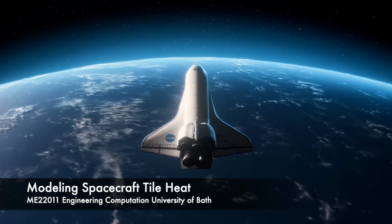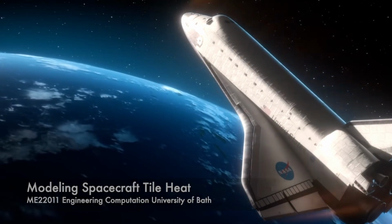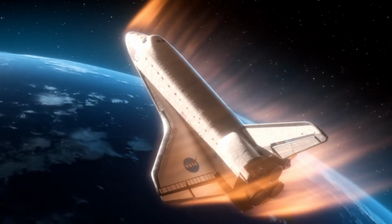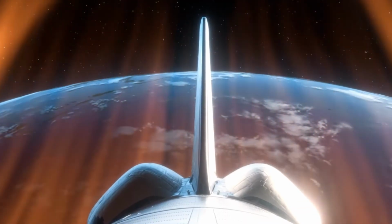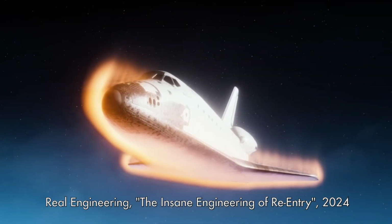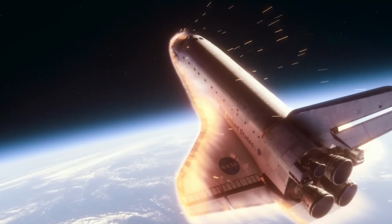During spacecraft re-entry, extreme heat is generated due to atmospheric friction, which can reach temperatures over 1000 degrees Celsius. To protect the structure, thermal protection tiles, like those used on the space shuttle, are critical. In this project, a single heat shield tile was modelled using a 1D heat conduction approach. The outer surface temperature is based on real NASA data, while the inner surface is assumed to be perfectly insulated.